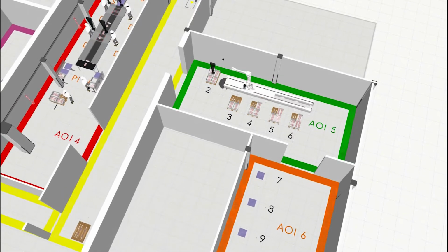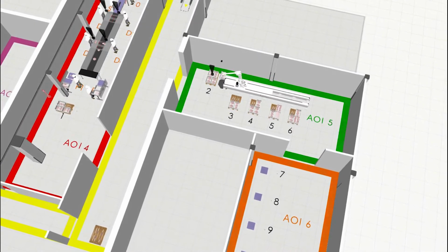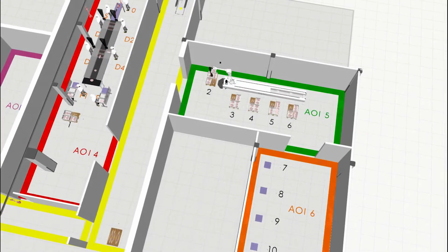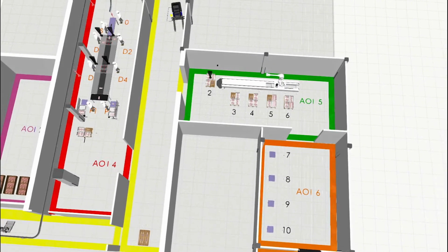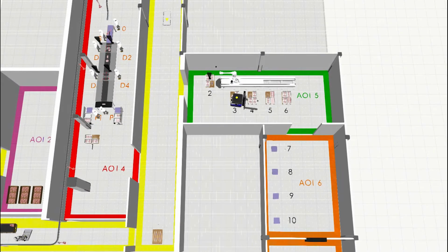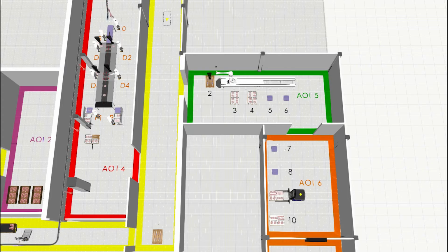is 1.6 m/s. To verify the reachability of the robotic arm in the workspace, a simulation and offline programming with the selected robot and track motion is performed in RobotStudio software. Based on the requirements and selection of the robotic system, a layout and visual components software is prepared. The selected robotic system is compatible with ROS Industrial and therefore simplifies the integration with OPIL.